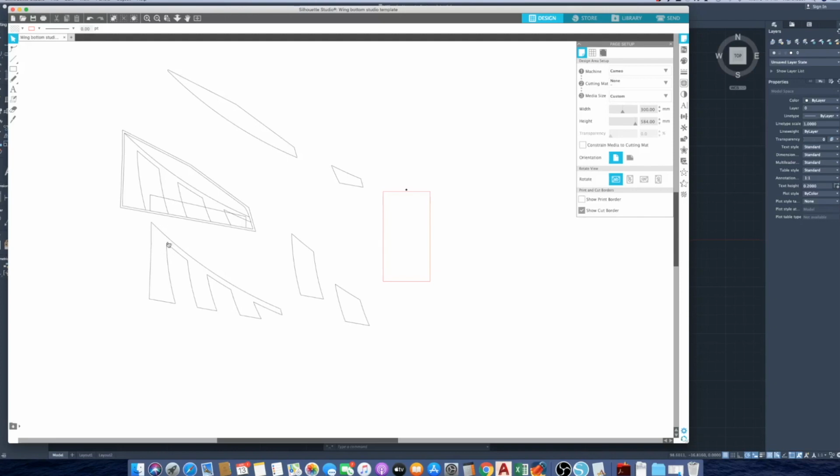So you really want to make sure that this geometry matches what you have intended. And if you do want to use your CAD files as templates, you won't be able to, because the geometries will be slightly off. It looks like they're pretty close, but they're not. So you really have to double check that all the parts match up.